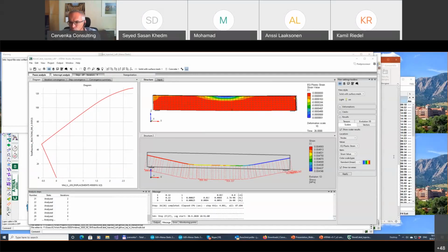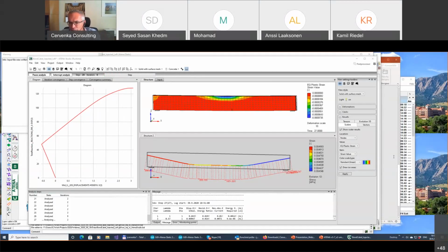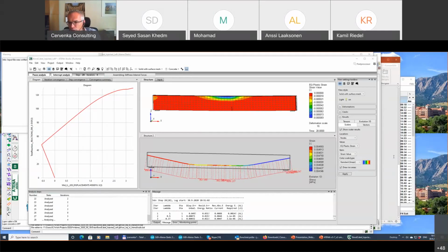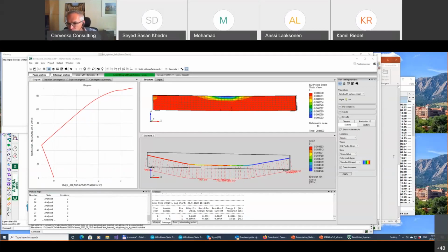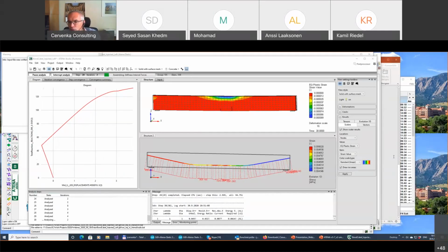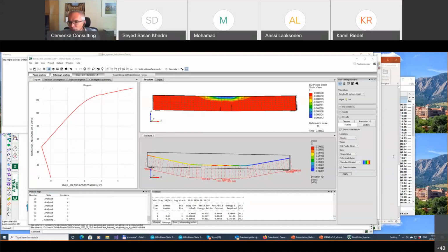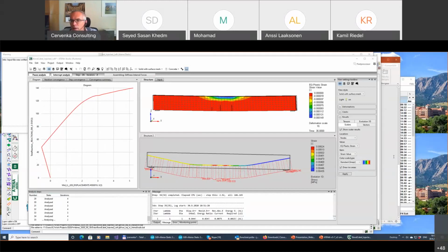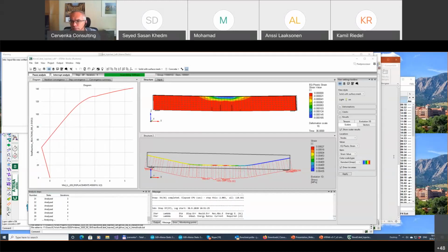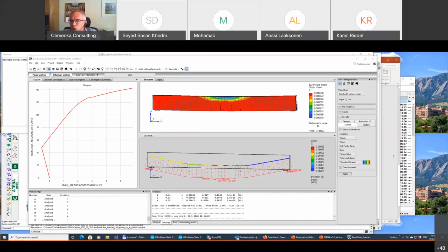So you will have to define some proper history: first maybe a corrosion evolution with constant load representing maybe the dead load. This may run for several steps simulating this corrosion process. And then at the end of these corrosion steps, you can apply the track load by moving the track across the bridge. So this can be combined.